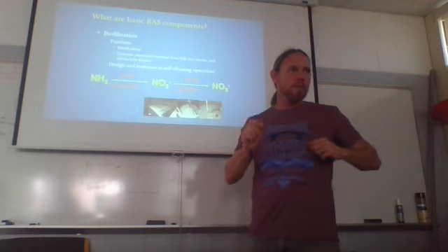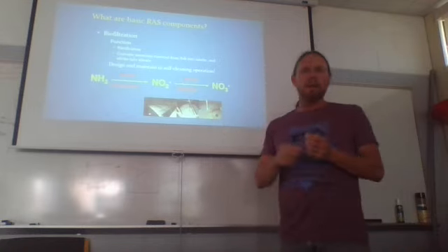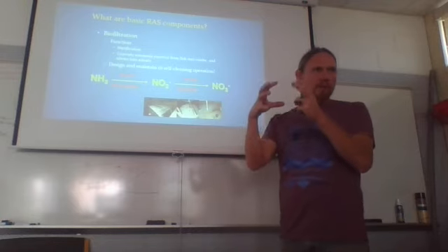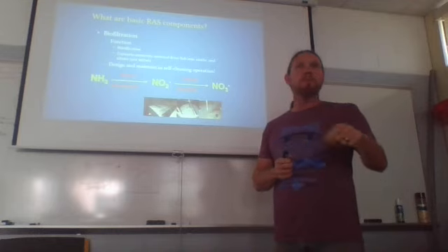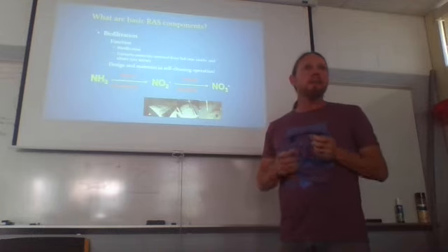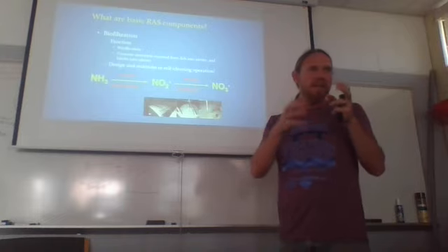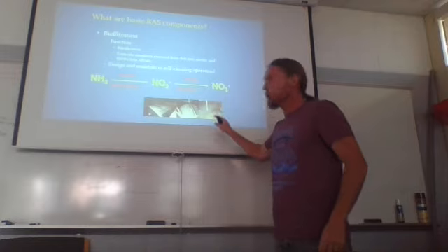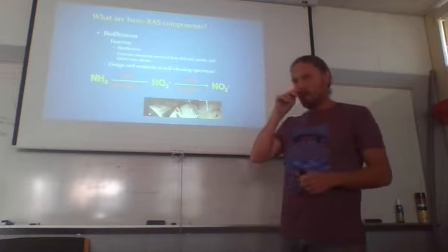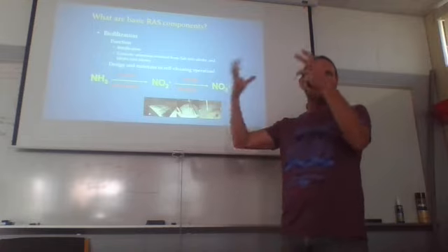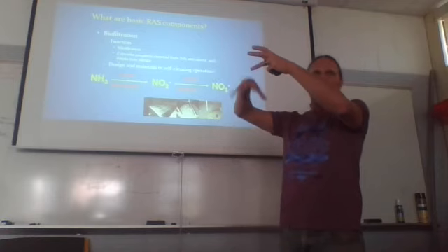But you don't want to go to too high of a surface area either, because remember, these are aerobic bacteria. And you can say, well, I got this brick here of sponge material that's got 10 times the surface area of that bioblock. But what can happen when the surface area gets too high, that means there's less and less space for water and air and gas exchange. And these things all work best when they're not completely submerged. They're either in a situation where they're tumbling around and coming in contact with the surface, or they're suspended above the water and there's water trickling over them.